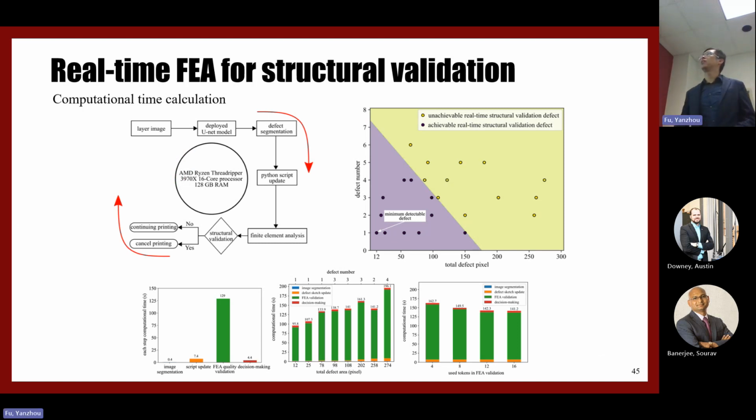In order to achieve the real-time FE analysis, we also analyze the time constraint. Here we use a more powerful computer with 16 cores, and we do the same thing to calculate the time. And here is the final result. You can notice that the image segmentation takes a very short time, but the script sketch update takes a longer time, and most of the time is taken by the structural FE analysis.